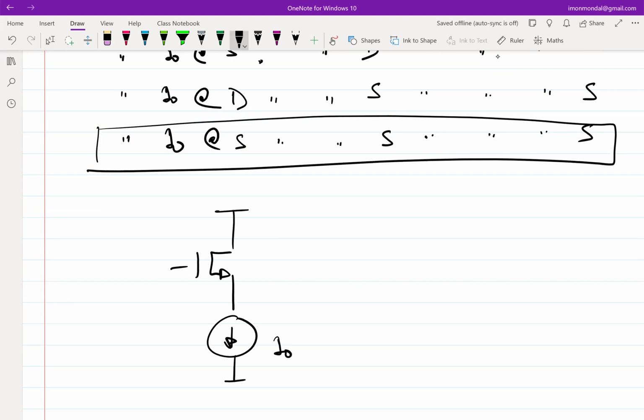So now if we apply the current source at the source, we are not touching the drain. So let's say the drain is at some constant voltage. Drain cannot be ground, because by definition drain is at a higher voltage. So just put it at the maximum voltage that is possible in the circuit, which is the battery VDD.